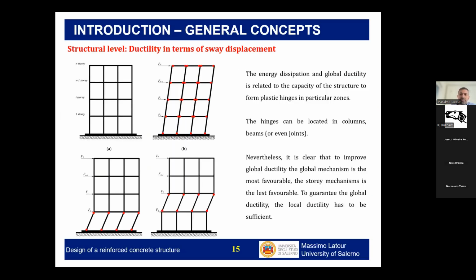This is the idea. So, concept which I have already underlined, when I go to the structural level, if my plastic hinges are able to sufficiently rotate to have some relative rotation in between the beam and the column, so a rotation that I'm calling here theta, at the point of the global hierarchy, the global level, the level of the structure, you see that for the same rotation, it will be possible to reach different lateral displacement based on the pattern of plastic hinges.